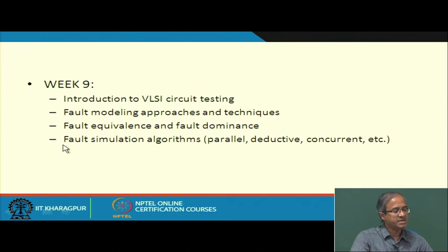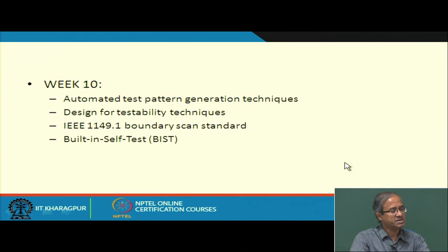Then we looked at some of the fault simulation algorithms, which are a very useful tool for the test engineers. We looked at some algorithms like parallel, deductive and concurrent. During week 10 we continued with our discussion on testing and looked at some basic concepts of test pattern generation.